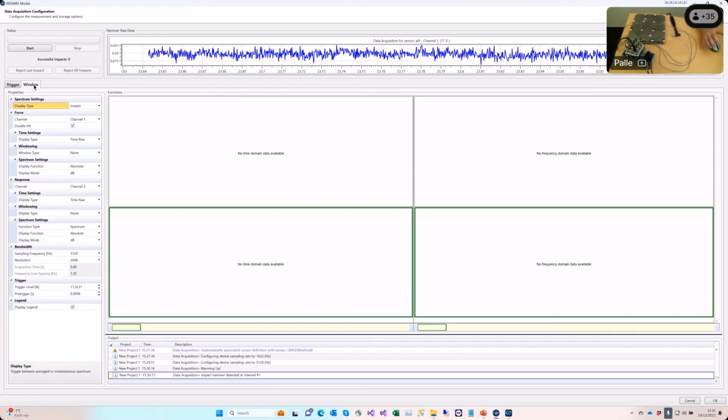We will start now configuring a force window. There's really no need not to apply a force window when you have a hammer here. At least I cannot see why you should not do it. So what I'll do is show the raw time series and the window that I'm going to define. I can do that by selecting this option here. And then I'd like to select a force window here.